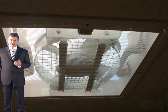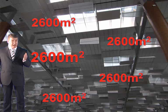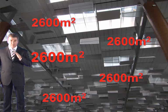Now, it's been decided to use mechanical ventilation in this stage, and therefore we're going to proceed with that in mind. Now, we need to determine, first of all, how many reservoirs we need. The largest size of a reservoir in a mechanical system is 2,600 square metres. In this case, it tells us that there's 2 reservoirs, 6 metres by 50 metres, which is well below the maximum.